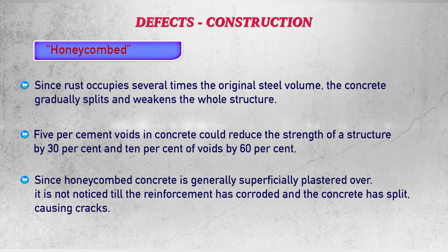Since honeycombed concrete is generally superficially plastered over, it is not noticed till the reinforcement has corroded and the concrete has split, causing cracks. If minor cracks by honeycombing and voids are not repaired properly, the disintegration would continue like cancer and result in a collapse of the structure.